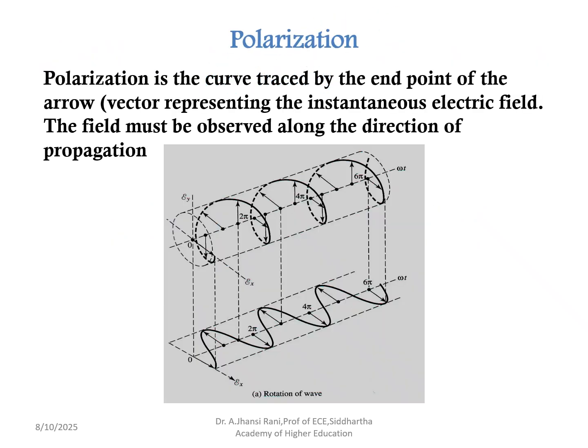See, polarization is an important parameter for antennas while transmitting and receiving. When the transmitting antenna and receiving antenna are both polarized in the same orientation or same direction, you will receive the maximum power. If the transmitting antenna is vertically polarized and the receiving antenna is horizontally polarized, minimum energy will be received by the receiving antenna. If the receiving antenna is also vertically polarized, then you will receive the maximum signal.